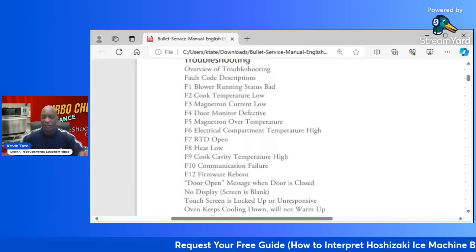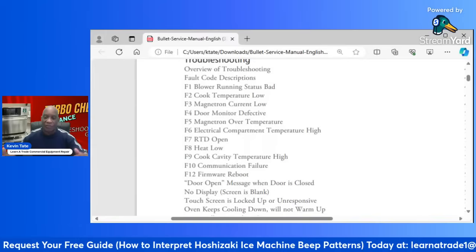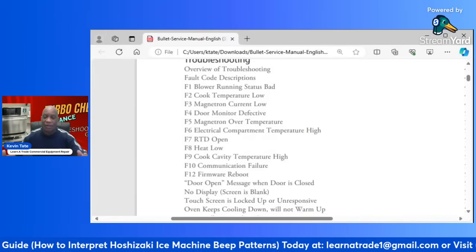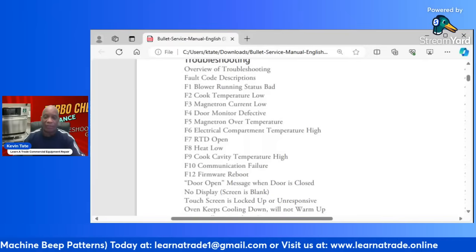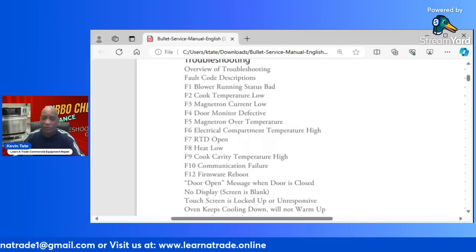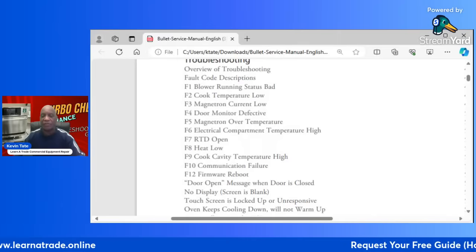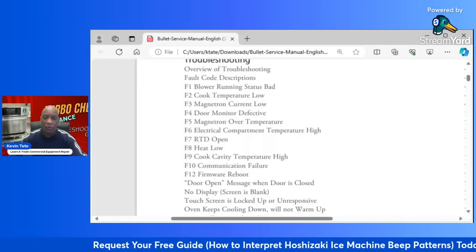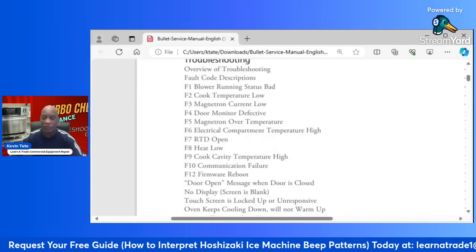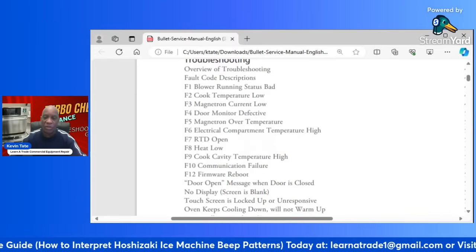The magnetrons have fins on them, and that air gets blown through there to keep that area cooler and to regulate the heat, because these machines get up to 500 degrees. So you need those cooling fans. Those fans are in the back, on the right and left side, and the whole time those magnetrons are turned on, those fans should be on.